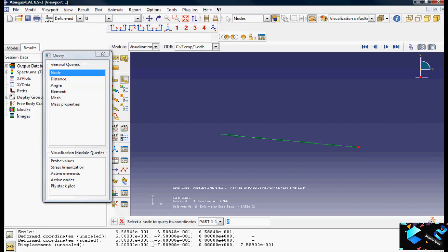And it's too stiff, 0.759, which is actually less than the Bernoulli beam, when in fact the Timoshenko beam should be less stiff, since it also allows for shear deformation. So the displacement here should be higher than the 0.8 meters that we obtained for the Bernoulli beam.